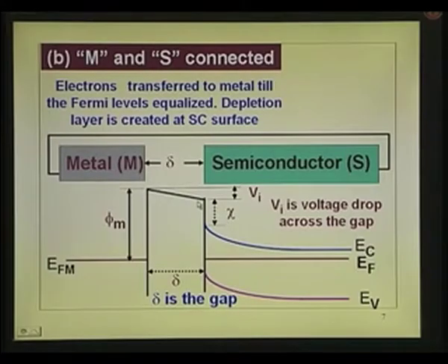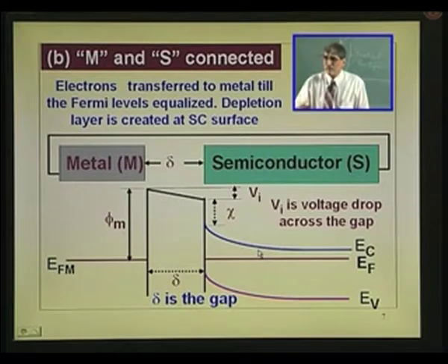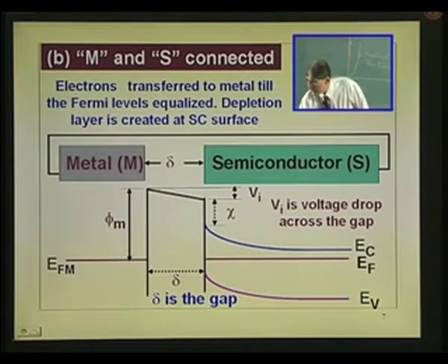That is the vacuum level. The vacuum level itself tilts now. So, this slope here indicates that there is a constant electric field, therefore, a linear voltage drop across that point. So, the conduction band or the vacuum level here is going linearly like that. And you can see this particular portion here, that is not linear, because whenever there is an abrupt junction, wherever there is a depletion layer, the voltage is square law. So, that is what is shown by this portion.